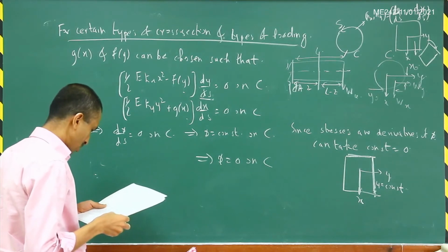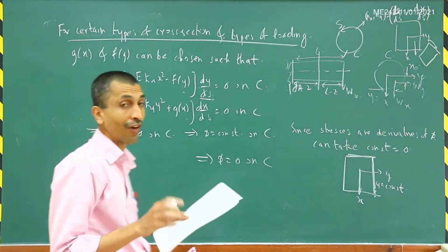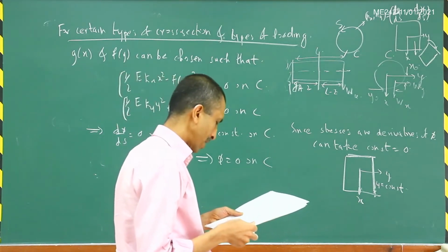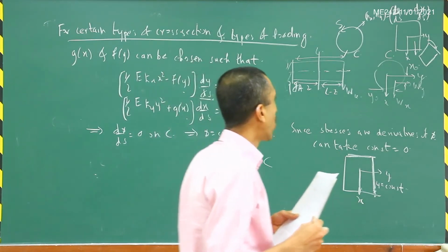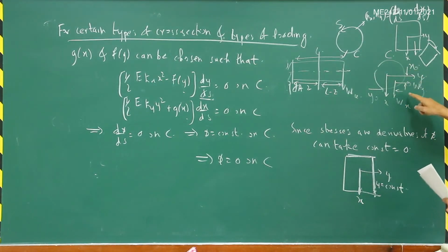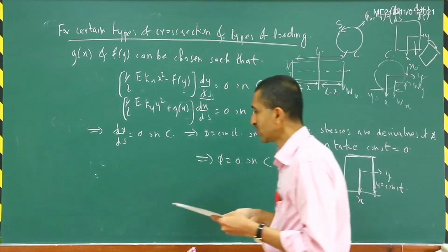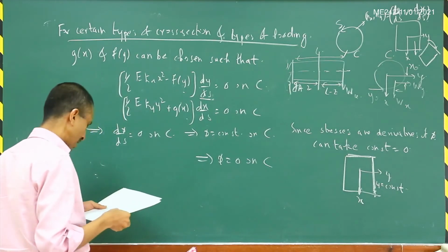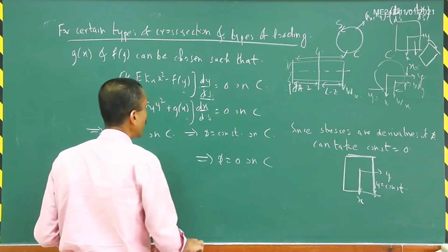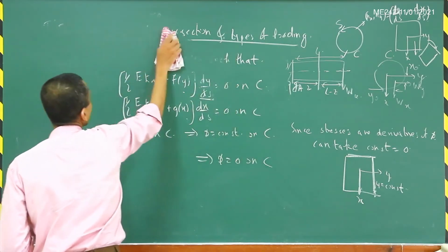Fine. Okay. So now, what about that alpha, the integration constant? We have still not talked about that. That constant is now obtained by looking at the moment equation about the origin. You can see that the moment is going to be given by x naught times w of y minus y naught times w of x. That moment should be equal to the integral of x tau yz minus y times tau xz. And so from that we will be able to get an expression for alpha.